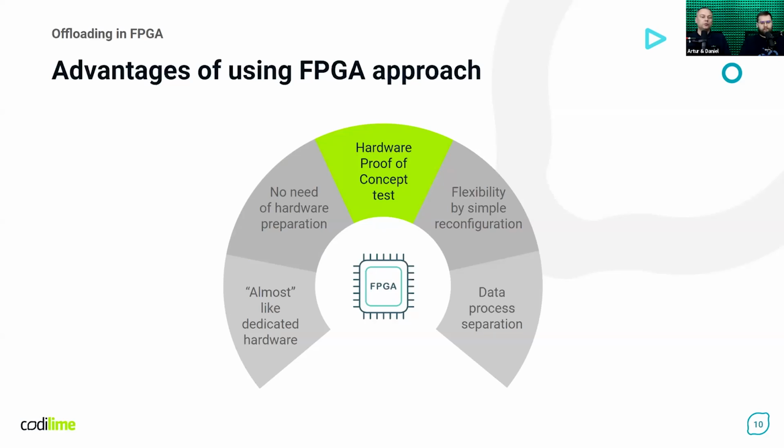If our proof of concept device runs well on FPGA, we may expect even better performance when prepared as a specialized integrated circuit. Preparation of an ASIC is as easy as sending files created during synthesis of our HDL sources to the integrated circuit manufacturer.